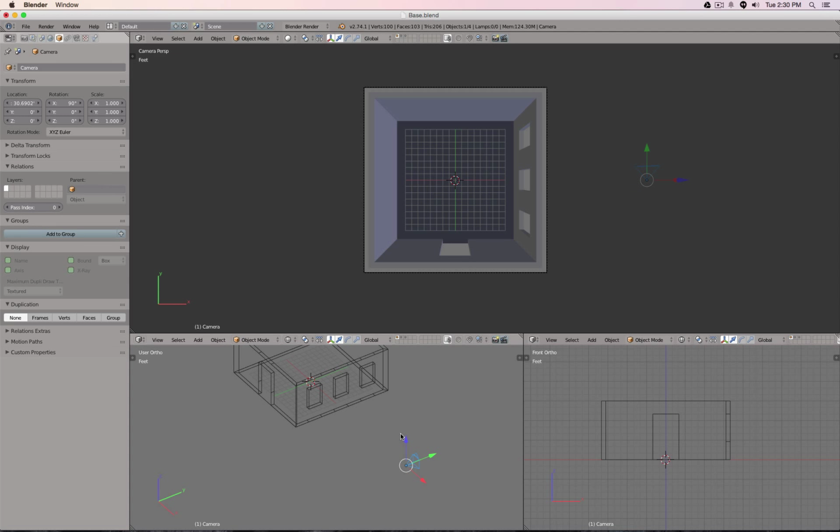Or I could also in my 3D viewer press R, Z, and then move my mouse so it rotates to the wall. And you see here upper left corner, I see the amount of rotation. So it's positive 90. And I can type in 90 and enter. Okay.